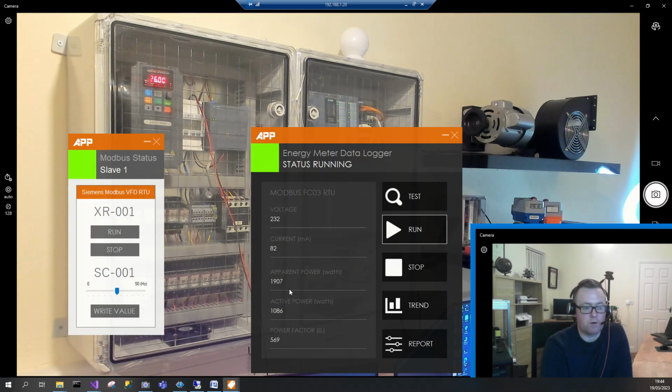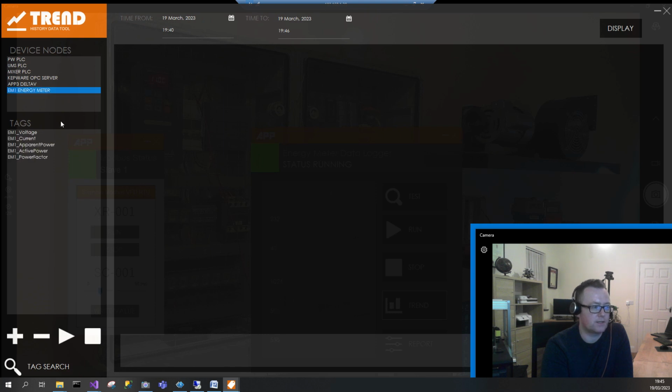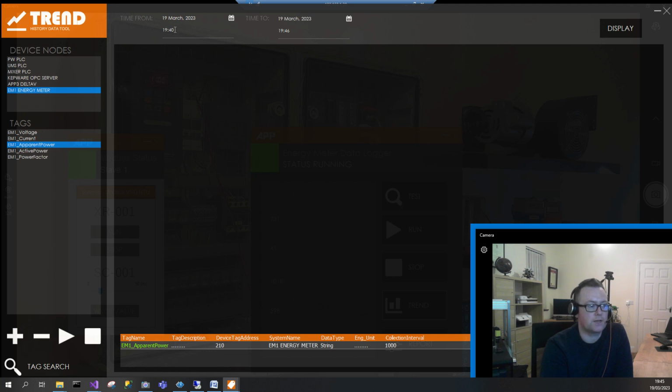And you can see that the apparent power has jumped up. The time at the moment is 19:45, so we'll go 19:45 to 19:46. Maybe I'll jump it down. And in real time, if I want to, I can take a look at a trend. So in this trend, I'll click the energy meter, take a look at apparent power, bring it across, and see how it's been getting on over the last minute that we've been looking at it.